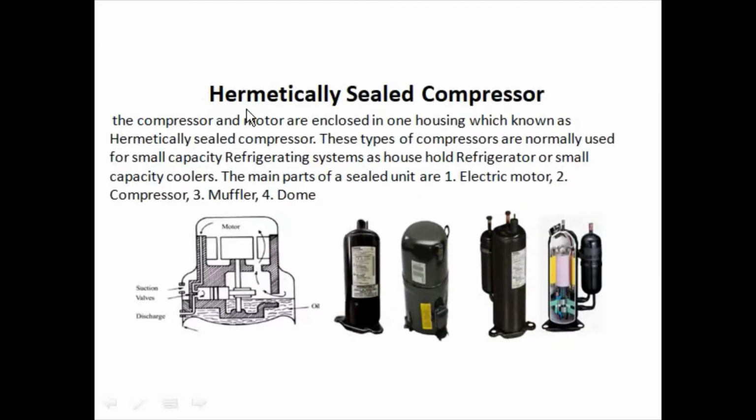Without wasting time, this is a hermetically sealed compressor. This is the image of the hermetically sealed compressor. For a hermetically sealed compressor, all the components, all the parts, motor and compressor, are constructed in these cases. The motor and its windings, everything is enclosed in this case, which is welded.